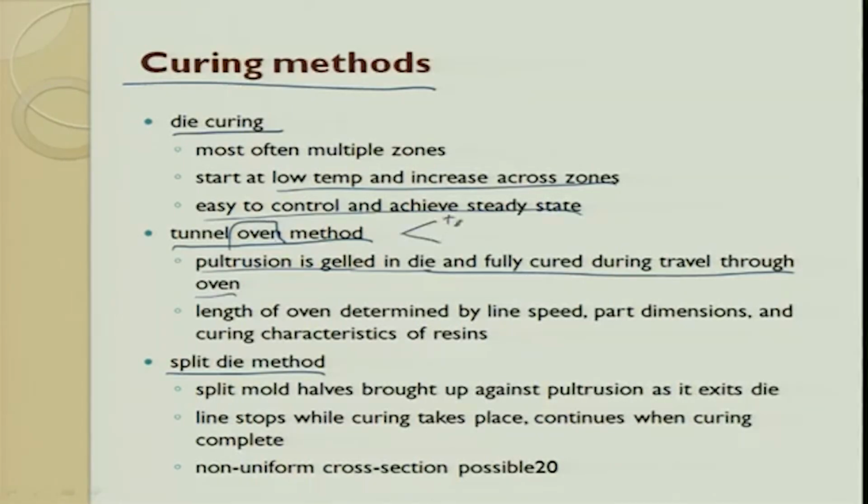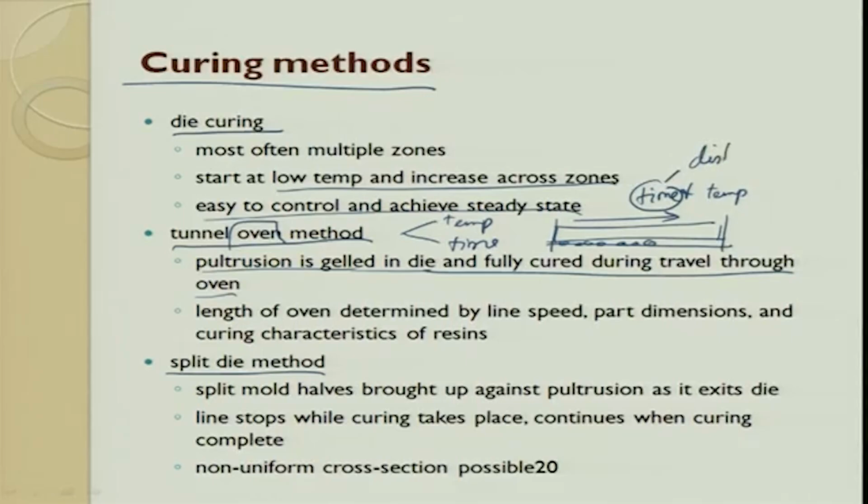What does that oven do? Oven has two things, one is temperature, another one is time. As the component moves, it takes certain time. So, you control the time period here and also you try to control the temperature. So, time and temperature is controlled. The time in turn is controlled by distance. That is why you see in pizza, you will always have an oven which runs along a length and it will be an endless conveyor belt which keeps rolling. The same way we can do here.